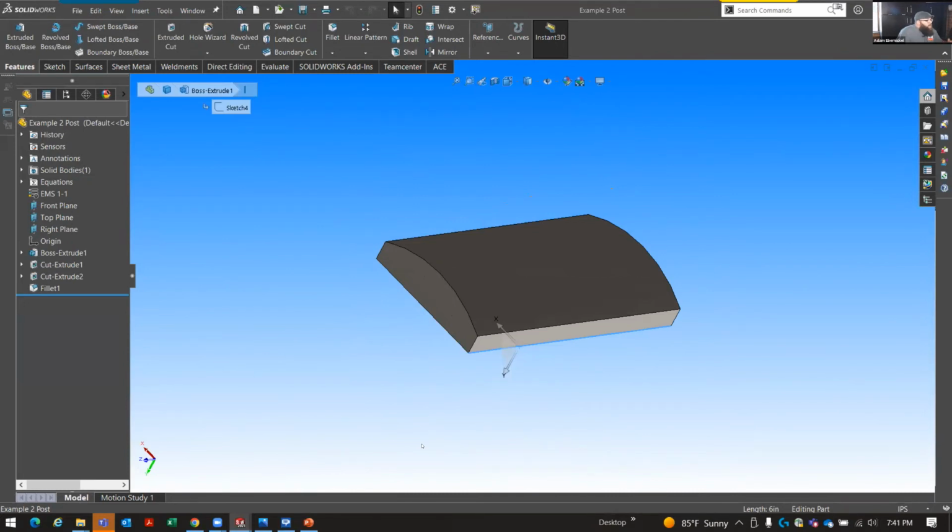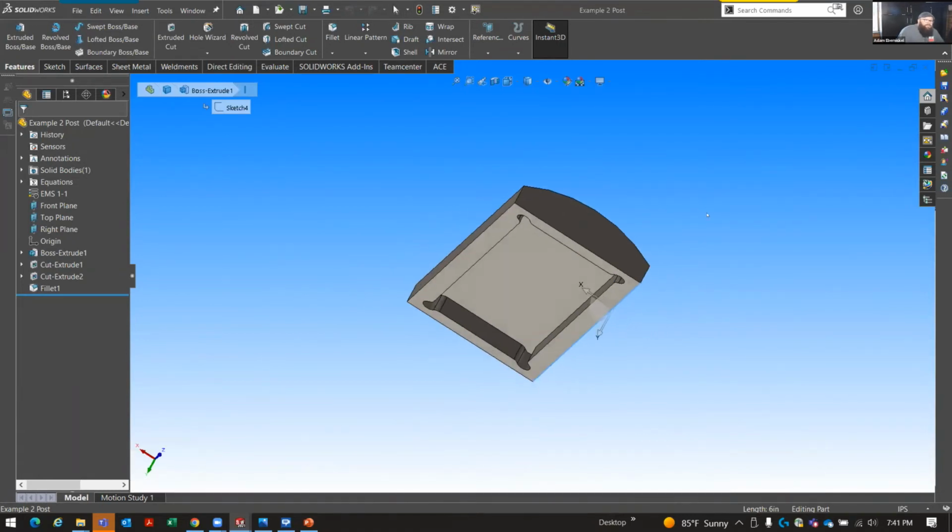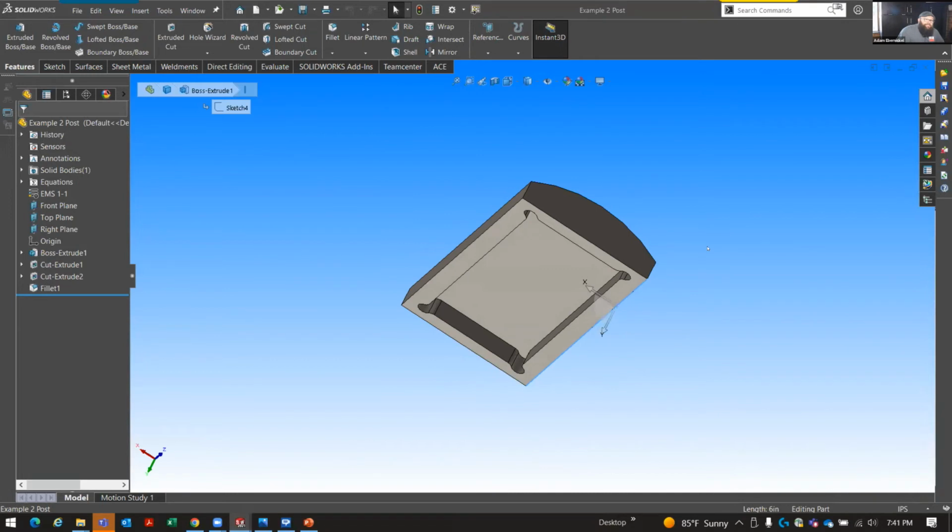I don't know how they did it because I never asked. All I know is that on most everything we do, it's 2 decimal places, so plus or minus a 16th. Because everything we do is 30 and 40 foot pieces of sheet steel that are getting bent sometimes 2 or 3 times and welded and hammered. Plus or minus an 1/8 is still pretty good.